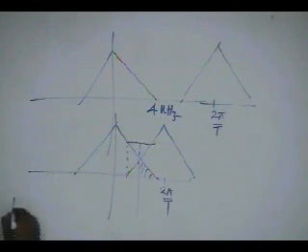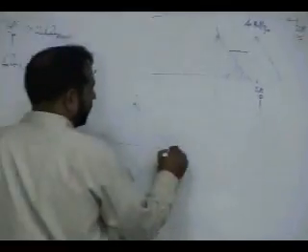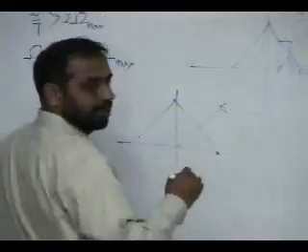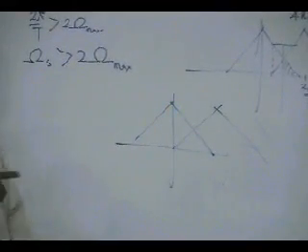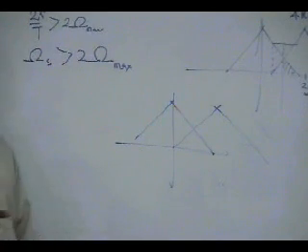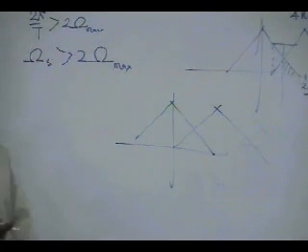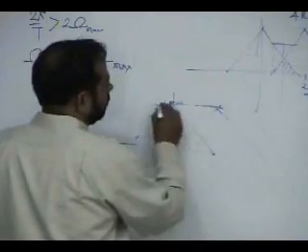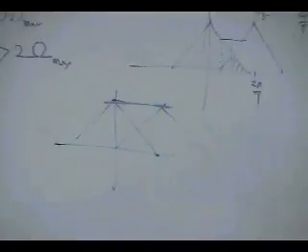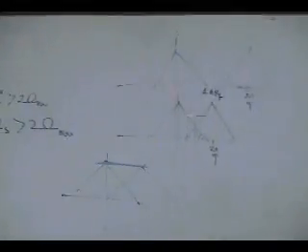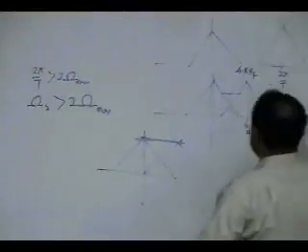So 4 kilohertz is this, and then you make a copy at 4 kilohertz. Every copy is at the sampling frequency. So if you sample a 4 kilohertz bandwidth signal at 4 kilohertz, you will get nothing, all garbage.